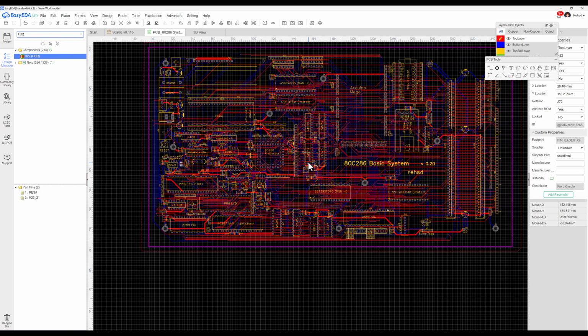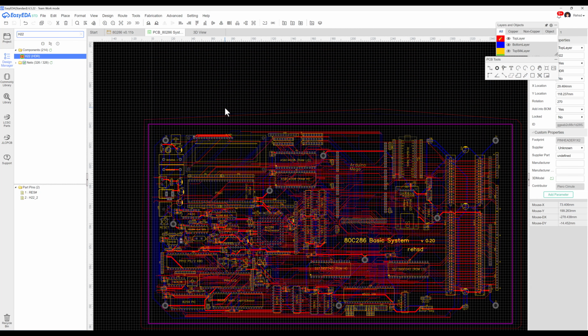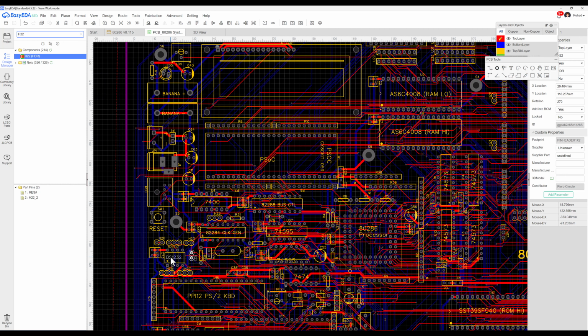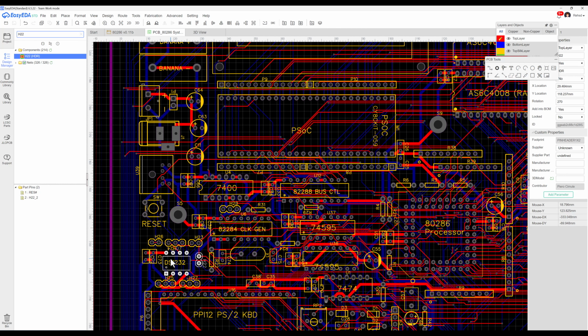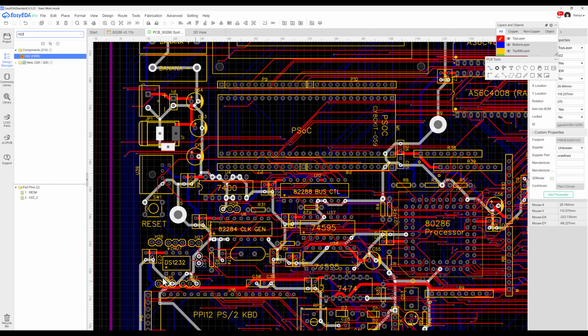Another is that the external card also supported reset. I could press a reset button, or when I power on, it delays and holds down the reset for a period of time. Someone had suggested maybe trying out a DS1232 to do that reset functionality, and so that is what I've done. You will see that down here I now have a new IC on the board. It's a DS1232. With that, I have a bunch of different jumper selectors around it.